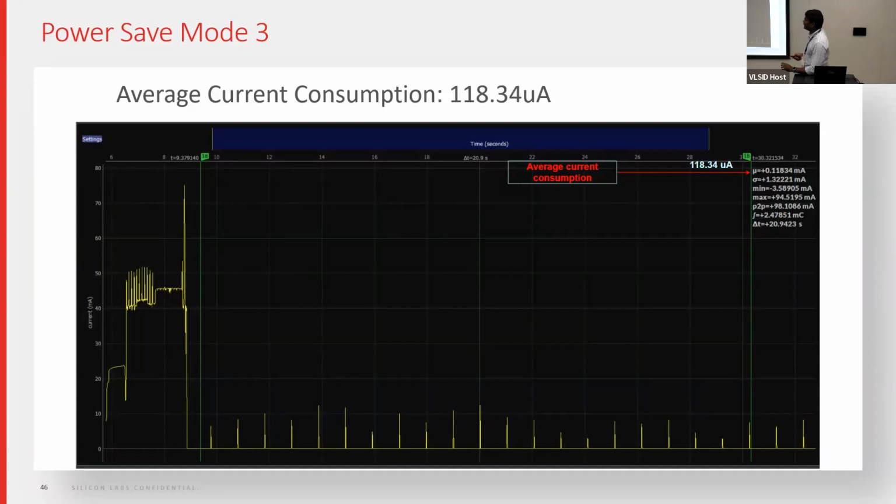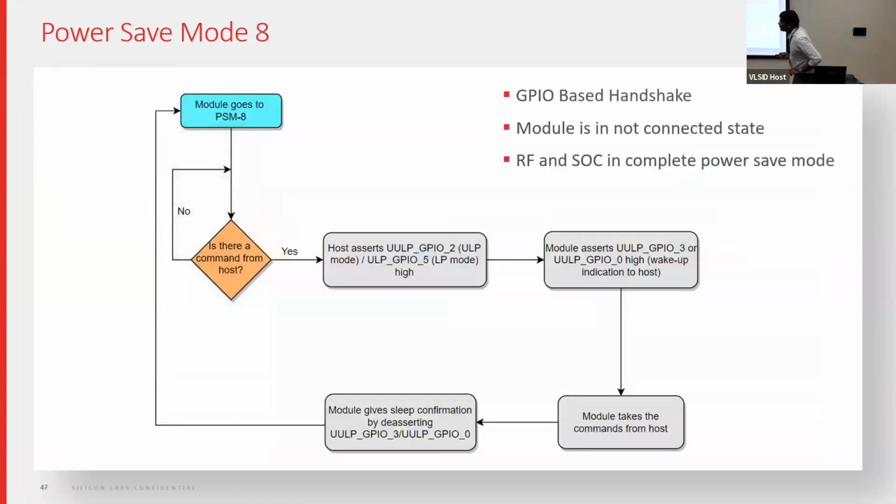Right. It will be the average power, because once the module resets and starts scanning for the access point, for example, if we turn on our mobile, first it will scan for the list of available access points. During that scanning phase, the power consumption will be very high, in the order of around 300 milliamps. Okay, so peak doesn't matter much. Right, peak doesn't matter. It will be the average power consumption, which is what we mean when we say power consumption.